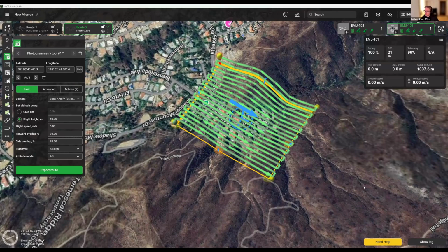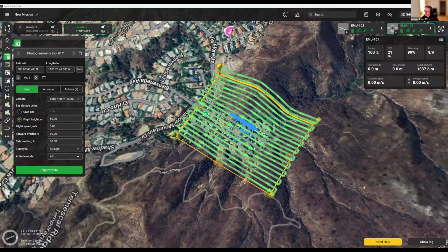So this is also what UgCS handles, because there are what we call VSMs, or vehicle-specific modules. A bit of a technical software term, but briefly what it does is it translates the route into the drone's format. And that's what UgCS comes built in with. So when you install it, you have options to select, for example, also the PX4 vehicles, ArduPilot vehicles. So you can basically choose what drone you want to use this for.